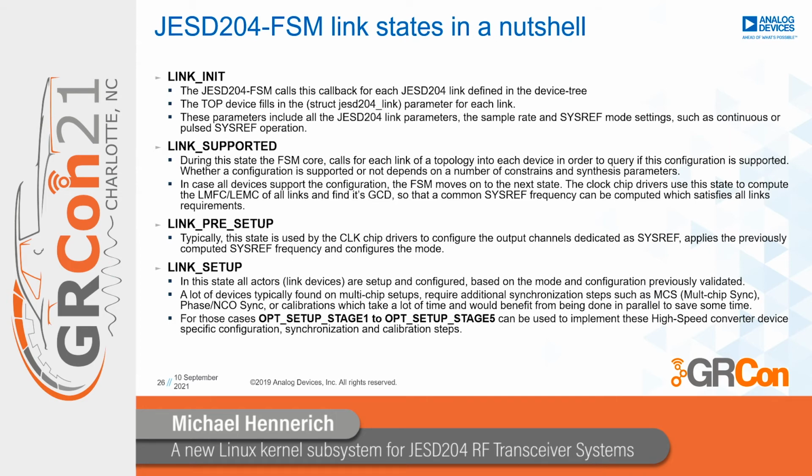In the link pre-setup state, this is typically used by the clock chip drivers to configure the output channels dedicated as sysref, and apply the previously computed sysref frequency configuration for the mode. In the link setup state, all the JESD link devices are set up and configured based on the mode and configuration previously validated.